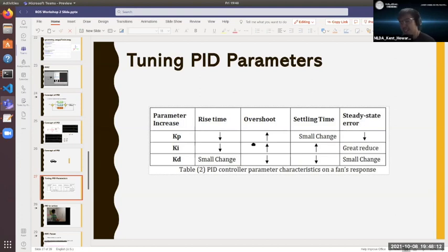There are some methods that are normally used in control systems engineering that are more theoretical in sense. There's the Ziegler-Nichols method for tuning. For systems, you can use system identification tools in MATLAB, in which you give it a frequency-based input and do a frequency sweep to tell the response of your system in order to tune your PID properly.